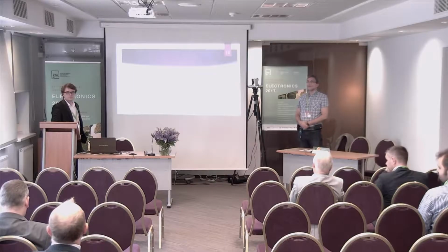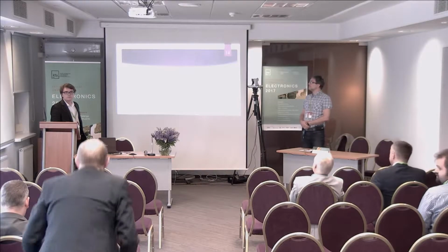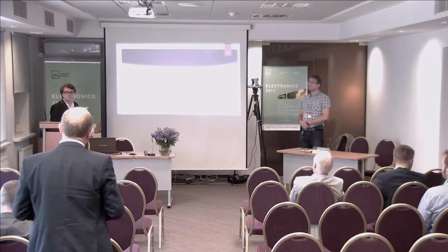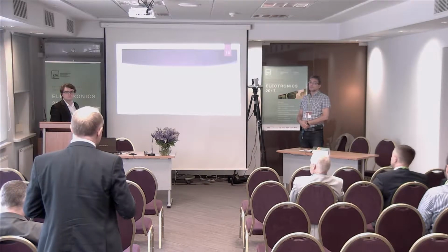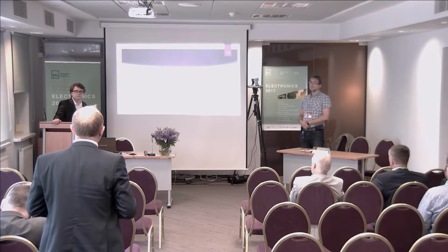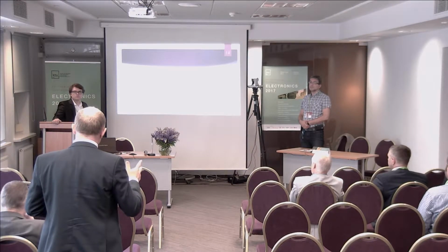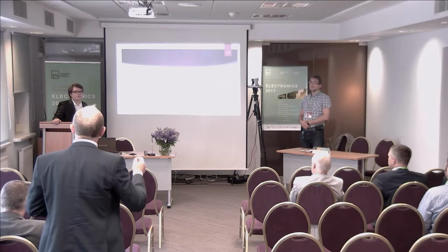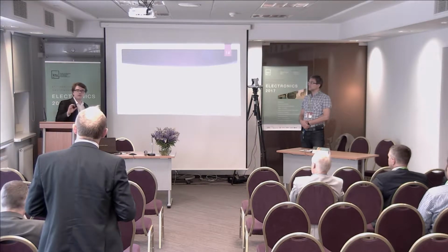For field strength measurements inside the GTEM, you have used a sensor. Yeah, an isotropic probe. Did you use a mechanical scanner? No, I did it manually, because any parts of a scanner, even if wooden or plastic, cause imperfections in the measurements, because the epsilon is different, and you know.